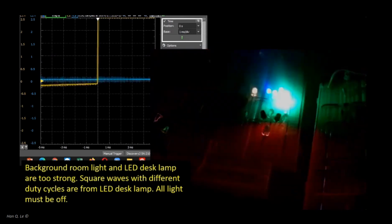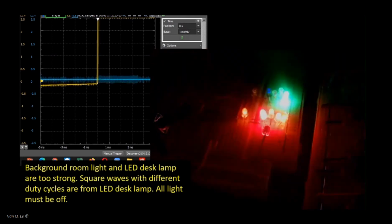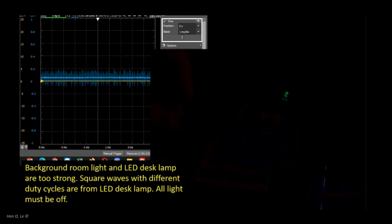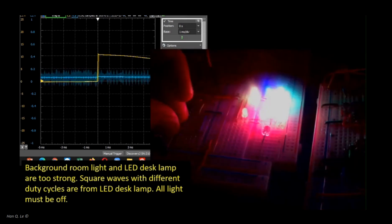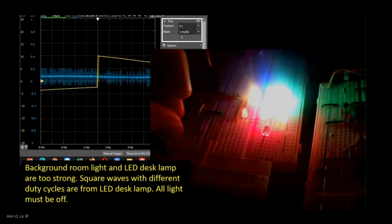In principle, all parallel LEDs should be of the same type. Here they are not, however, they were grouped together according to the band gap, or contact potential. Low band gap materials, yellow, orange, reddish, were parallel in one row, and the high band gap type, green, blue, were in another row.